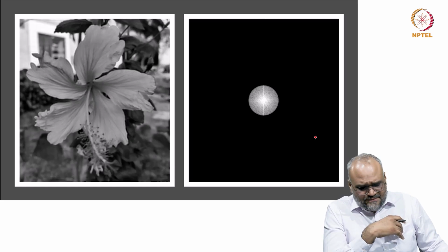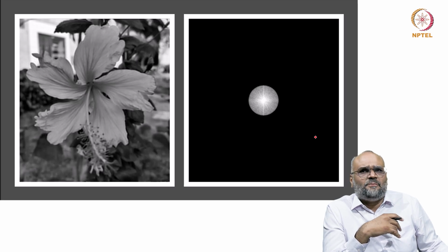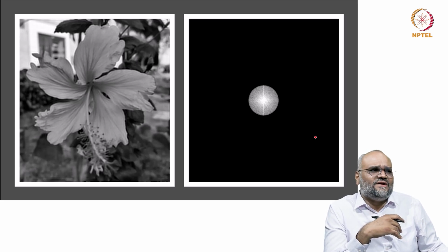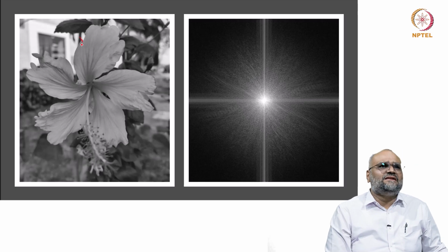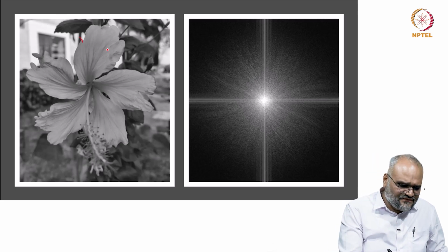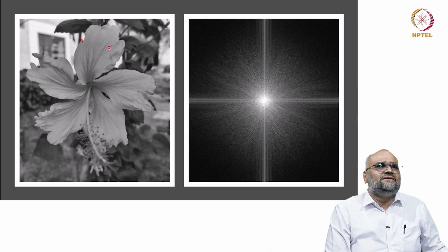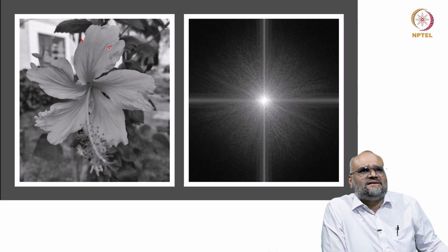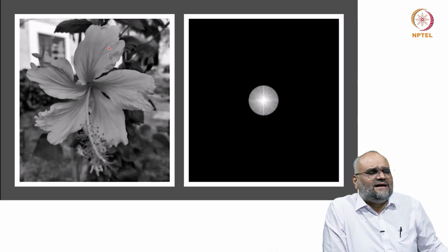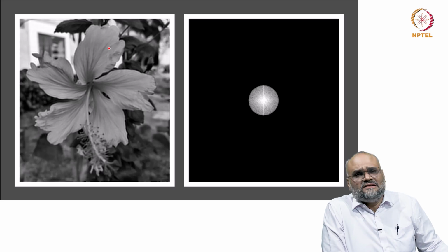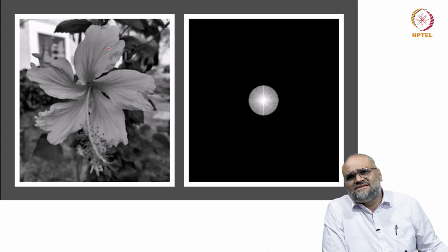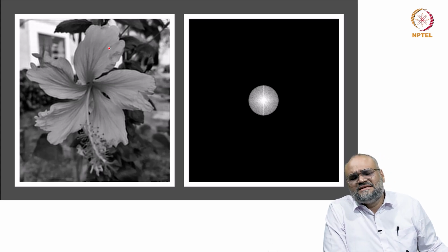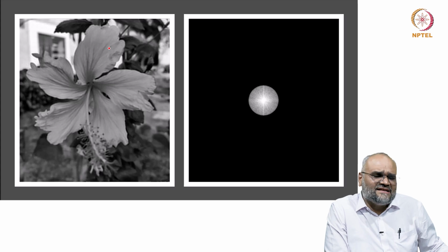And if you see, if I use a low pass filter which is allowing only the low frequencies, these sharp edges which are visible reasonably good and these features which are appearing sort of focused will now become more blurred here. This is what your low pass filtering does, and this gives you an idea that the resolution of your imaging system is only as good as the higher order frequencies that your imaging system allows you to pass through.